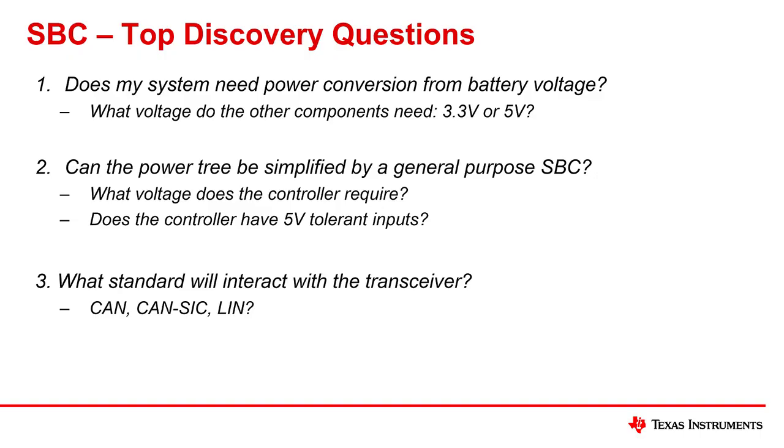The second question is always going to be a bit trickier to assess. A good measuring stick would be to look at the controller supply voltage. CAN devices are generally going to operate at 5-volt supplies, while many MCUs are operating at 3.3-volt supplies. The third question is going to depend on the use case.